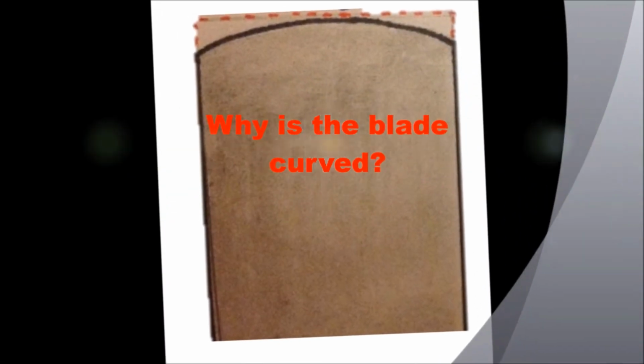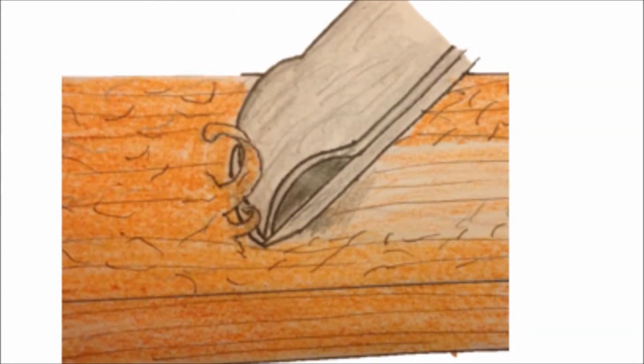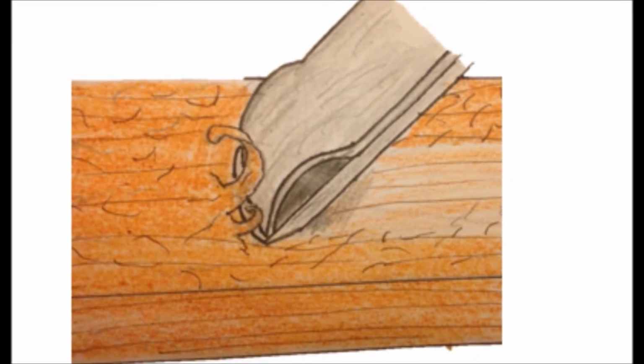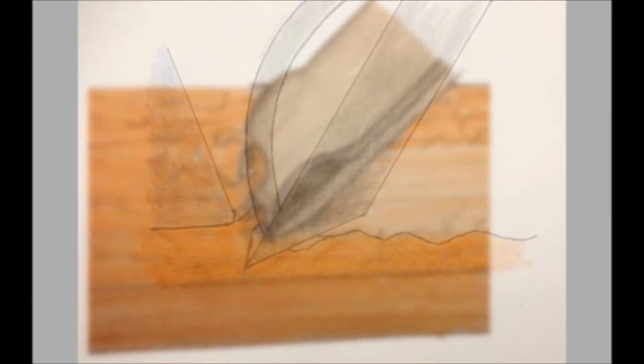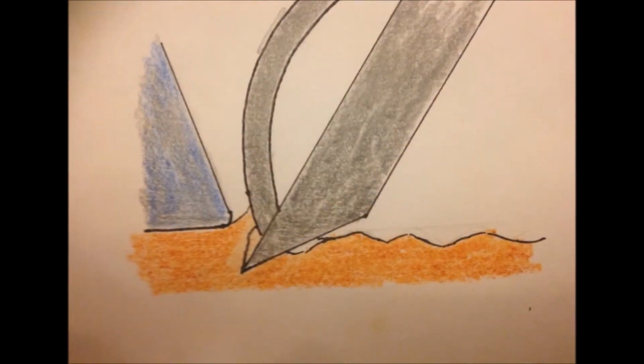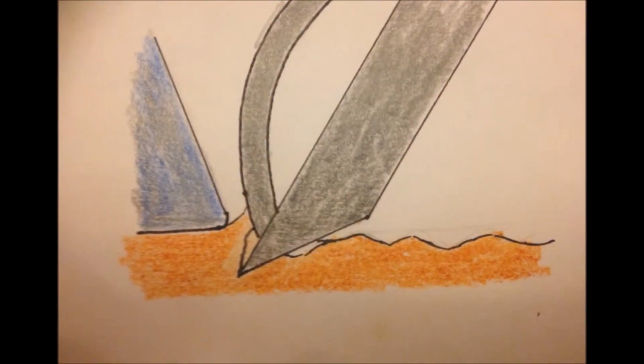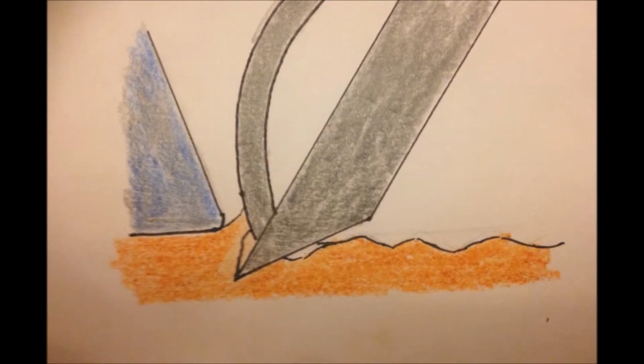In the jack plane, the cutting iron is curved. This allows for heavy shavings to be removed easily without making dig marks into the surface of the timber. As if the edge was perfectly straight, the blade would have a tendency to dig into the high or low areas in which you are planing. The blade has a 3mm camber for this reason. A camber is a slightly convex or arch shape on a horizontal surface, as shown in the diagram.